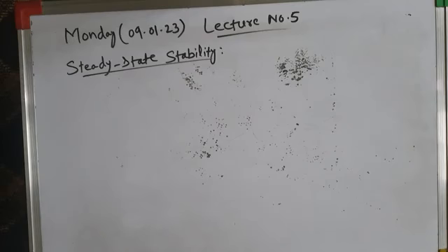Well, when we know about the load torque characteristics, and we also know about the motor speed torque characteristics, it will be very easy for us to determine the operating point. The operating point of an electric drive will be the point of intersection of the two characteristics.